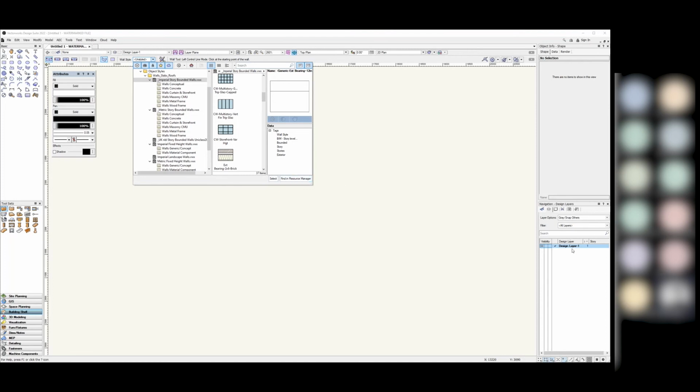But instead, we know that we can set fixed heights based on our layers, which is a much faster way to edit. So essentially what I'm saying is that when I'm choosing from this drop down, I want to make sure I'm choosing a metric template, preferably fixed heights. In here, I can now choose my different wall types.